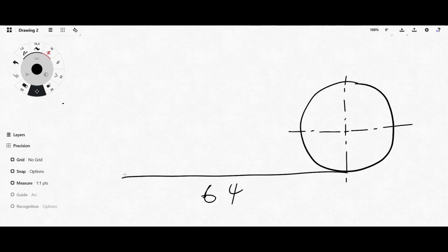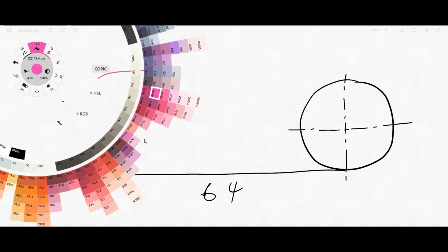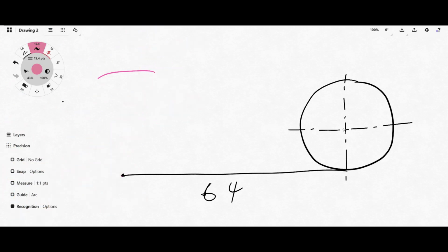From there, you can go on to finding the center point of the second arc, right? Like we did from the other end, you stand here with your compass, open a radius of 51 millimeters, and draw an arc. Then you stand here with a radius of 71, because it's 51 plus 20, and draw another arc.